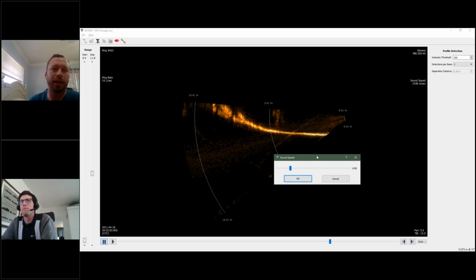To go into that kind of application, we would essentially get into survey grade software, which the BV5000 can integrate into, for example, Teledyne PDS software, to collect data from that application. And you can input profiles, live sound velocity, position, heading, motion sensor information as well to collect data that way. But in ProScan, we do not take in those external sensor live data streams.